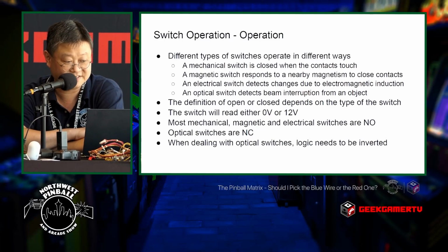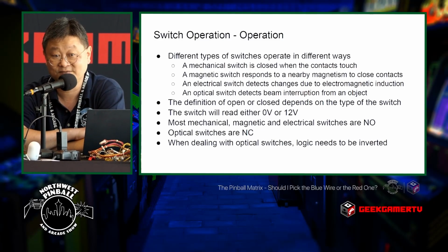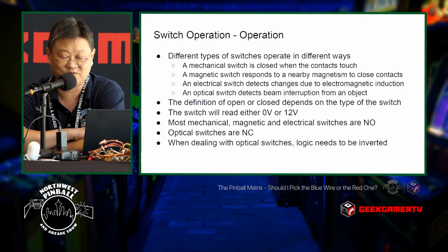An example of this is if you line up at a traffic light, you'll often see those little wires in the street just before the traffic light, the square that's buried in there. That square is one big giant inductor. And it's detecting the presence of your car, which is one big giant piece of metal. That change in current flow is detected and says, oh, look, a car just lined up at the stoplight. I need to change the light. That's why at 1 a.m. in the morning when you're driving home, you line up at the red light, it suddenly changes to green because it can see you there. It's the same principle. It's just a magnetic switch, an electrical switch detecting a magnetic change.